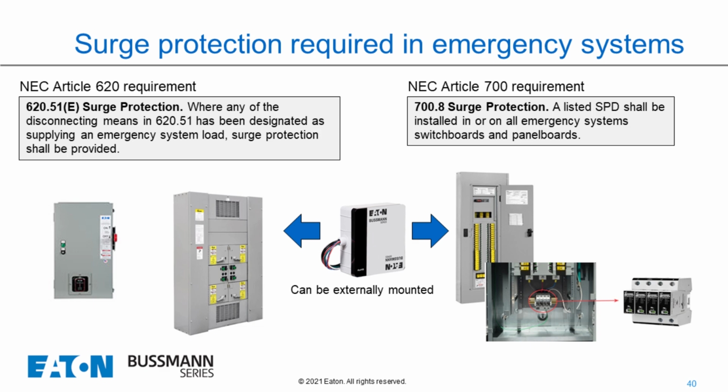This way you can see the light on, and when the MOVs sooner or later go, you would have to change them out, and you can see that. The one on the far right does have lights as well, and it'll turn red when they no longer are good, and then you just pop out the middle section and put it in. You don't have to unwire any of the stuff on the right. The one in the middle, the external one, you would have to unwire.